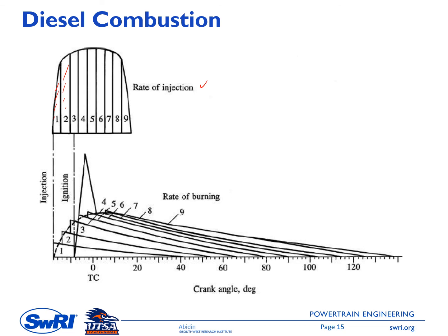As you can see here, there is also a dashed line. The mixture under this dashed line is a ready-to-go mixture for burning. However, the ignition will only start after a certain period. Between this point and this point, it is an ignition delay.